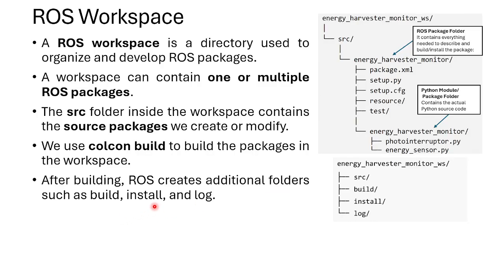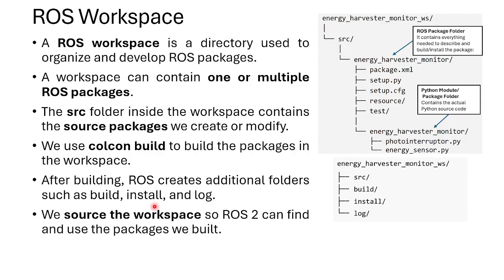Now that this is ready, another very important step is that we'll have to source the workspace so ROS2 can find and use the package that we have built. It's important to understand that even though we have built everything, ROS doesn't know that there is a package. So we have to introduce ROS to the package and tell it that this is the package you need to act upon.